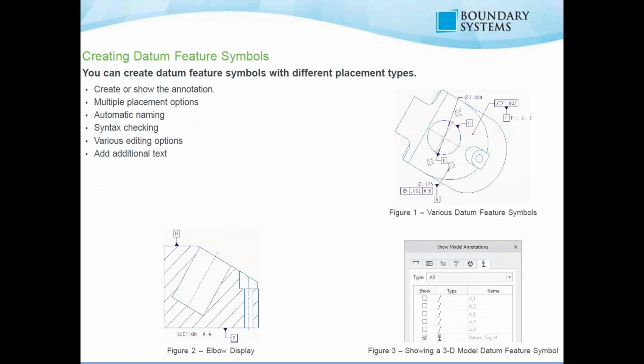Okay, so if you decide to create these at the drawing level, certain references can be selected, like edges, a point on a surface, or a dimension, or a GTOL can be attached to also, as we see in figure 1, different attachment types. And then after the fact, you can always modify by adding additional text and things of that nature to the actual feature symbol.